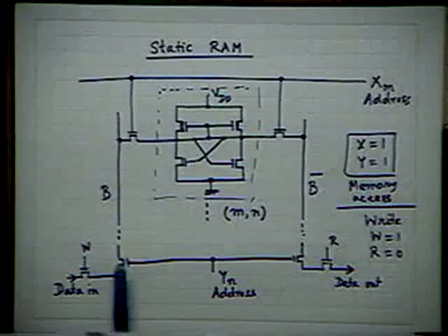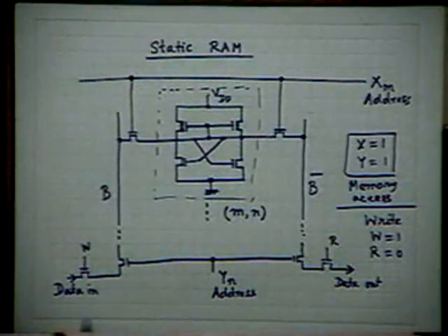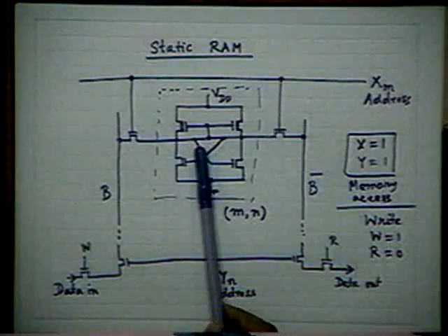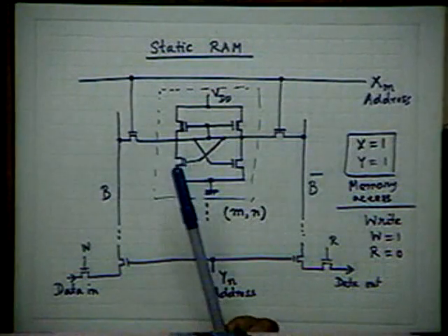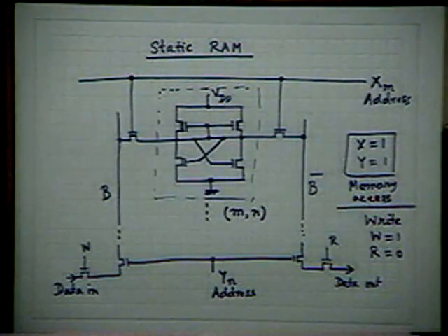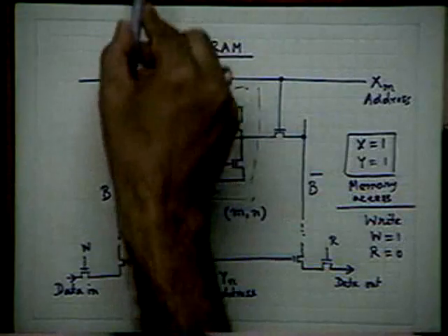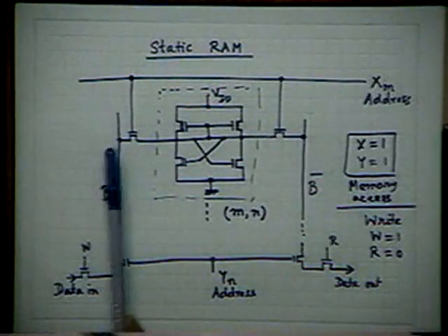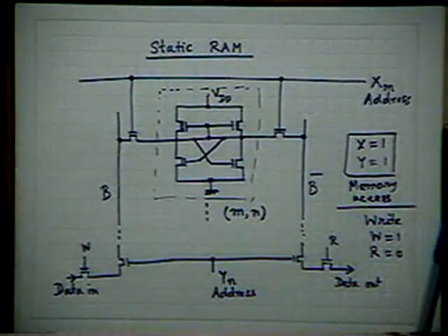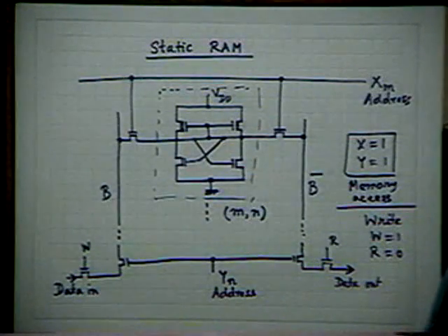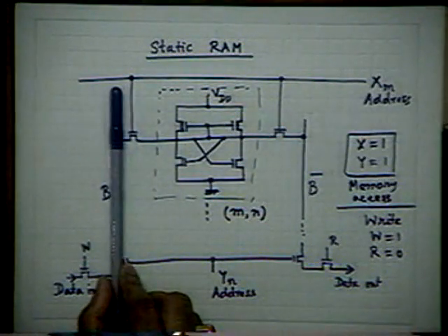You see that this bit line, as I said, is a very long line. I said that it is 100. 10 kilobit is a very simple example. You know that 64, and now recently, as I was mentioning, I found a paper where people are speaking of a 2 megabit SRAM. It's a very big thing. So you just imagine how long the line is. And this line provides connection to so many elements. Then what will be the total capacitance?